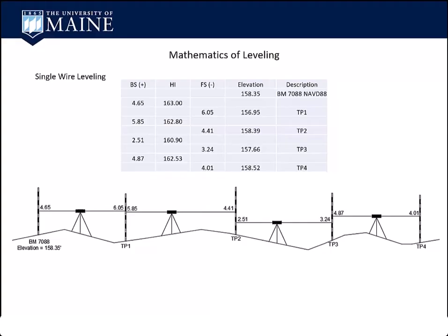And datums aren't far apart. I mean, 29 and 88, they're within 3/4 of a foot or less in some places. So it's difficult to tell them apart. So you have to give that metadata. You have to put in the book what you're doing so that it's understood. We have to be very clear with our notes.